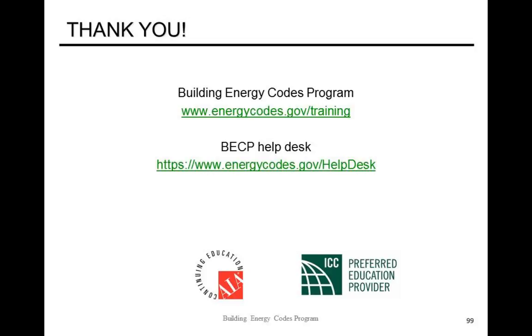Typically, there are end-use meters in energy modeling programs that allow you to get the energy use of different systems in your building, including plug loads, HVAC, fans, lighting. So the unregulated loads can typically come from the metered end use. There's just a number of different ways to do it depending on what kind of simulation program you're using. But if it's metered separately, that's the easiest way. That's the way I would do it. But also getting out hourly and annual loads from most simulation programs would be the way that I would do that.